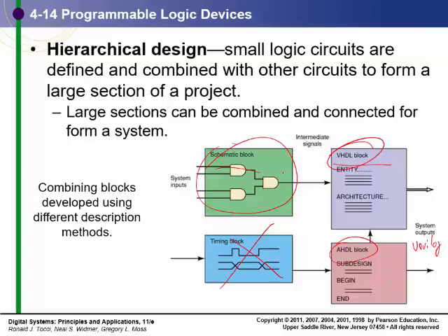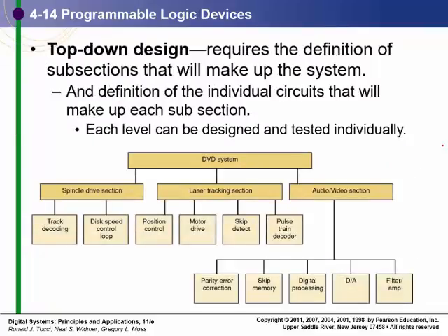So we can design hierarchically and put different blocks within. That makes our designs much more efficient, much easier to manage when we get into larger designs. And we'll talk about that later on. I have a lab that you'll do with an adder, where we design a simple adder and combine them to make a 4-bit or an 8-bit adder by simply adding the blocks up. Top down means that we can design each section separately and tie it into the single chip.